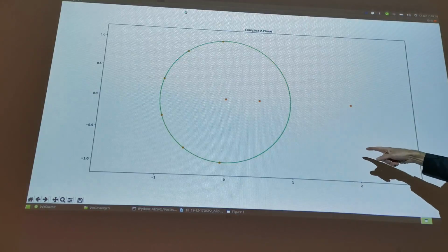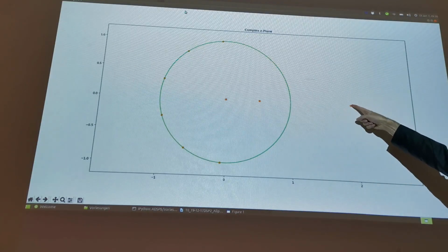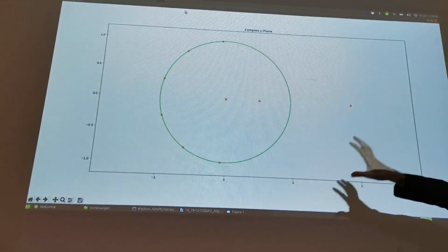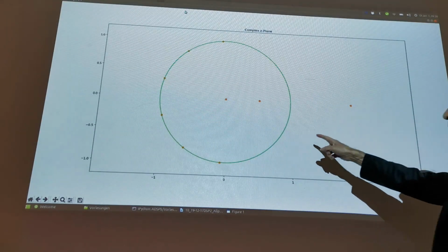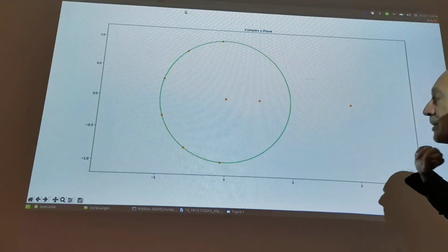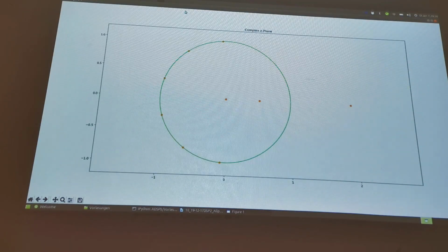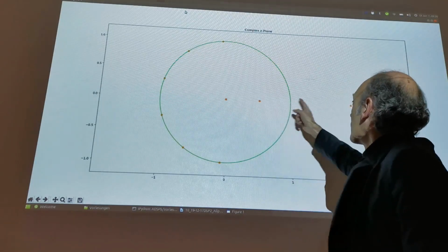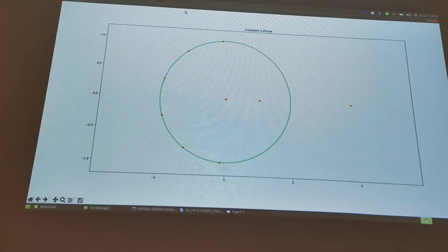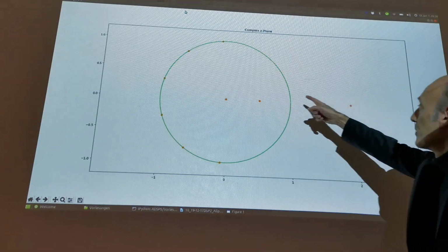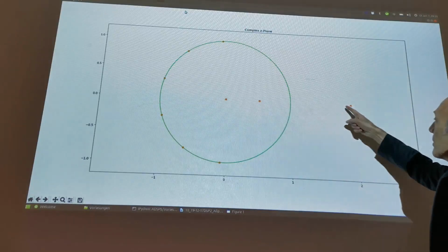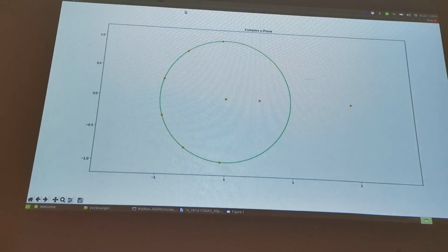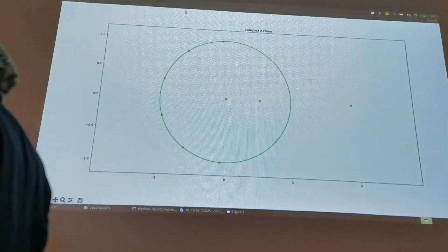And the most interesting pair is those. So one is close to 2 and one is close to 0.5. Can you see it? Yes. So this is actually characteristic for linear phase filters. Linear phase filters have zeros which, it turns out, are conjugate reciprocal around the distance from the origin. So this is around 0.5, this is around 2. So one is 1 over the other. Right? So they are reversed.